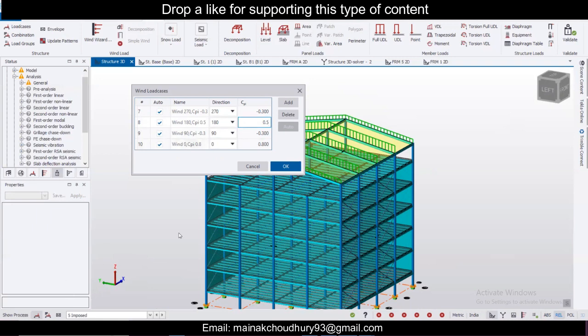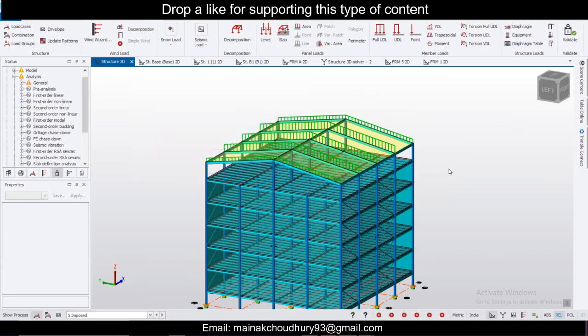So now we go along the y-axis. Now for the y-axis also, the windward side and the leeward side. So along the windward side minus 0.8, okay, and this one will be minus 0.5. So windward side, leeward side CP applied. And if you want to apply CP more accurately, you can go to table number 5 and 4 of the IS 875, and you can check this. Okay, and then you can click on OK, and then the wind has been defined.